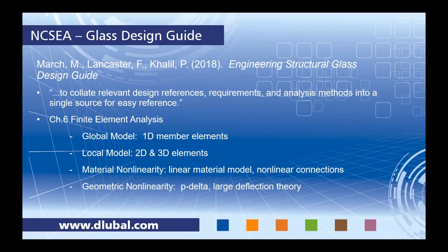As far as material nonlinearity, the design guide states that glass is a linear material model. Well, we also consider it an isotropic linear elastic material, but that nonlinear connection should be considered. Now, this might be more relevant for something like point supported glass. We can also take into consideration these nonlinear connections with things like contact solids, and we don't have time to focus on something like point supported glass connections today, but I do plan to do a follow-up webinar sometime within the coming months to maybe more focus on this.